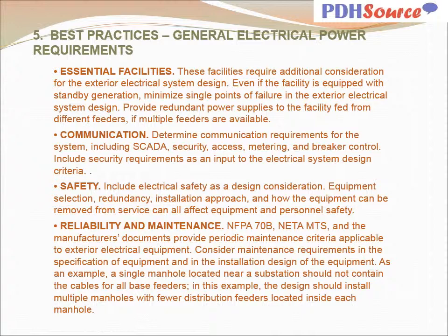As an example, a single manhole located near a substation should not contain the cables of all base feeders. In this example, the design should install multiple manholes with fewer distribution feeders located inside each manhole.